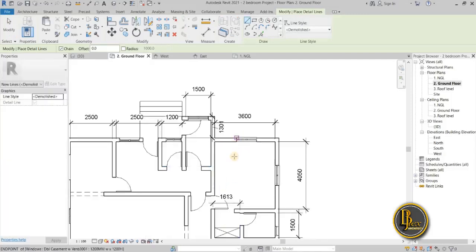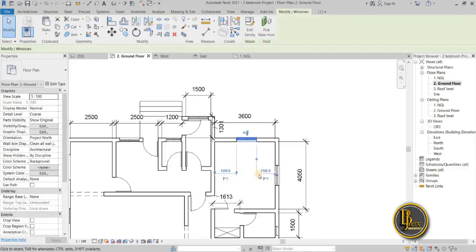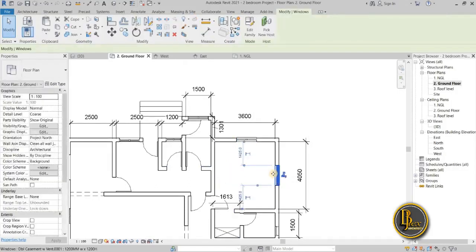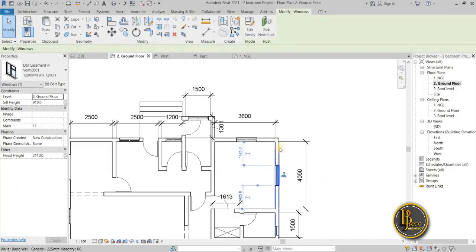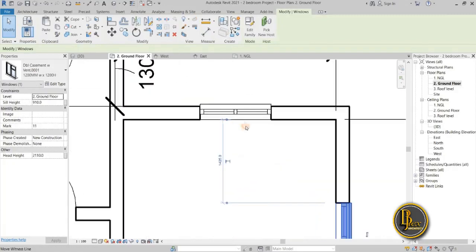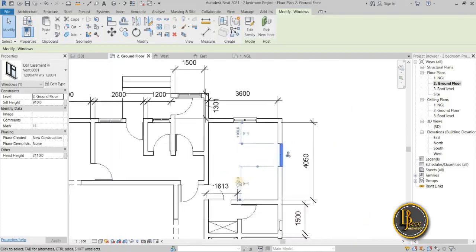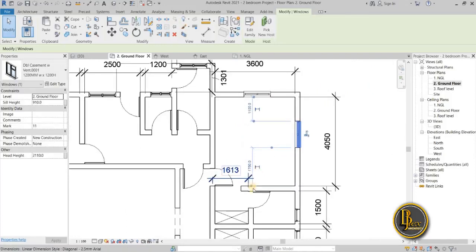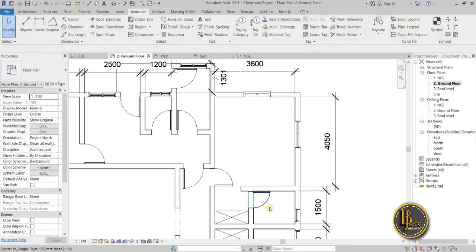I just want to do it once so that when we are putting a line dimension, we're just placing it on an already measured floor. So this is looking good. Right, for this we're having this place to be about 1,100. So let's change this to 1100. So this is 1,750, which is very correct. Alright, so let's delete this dimension now.